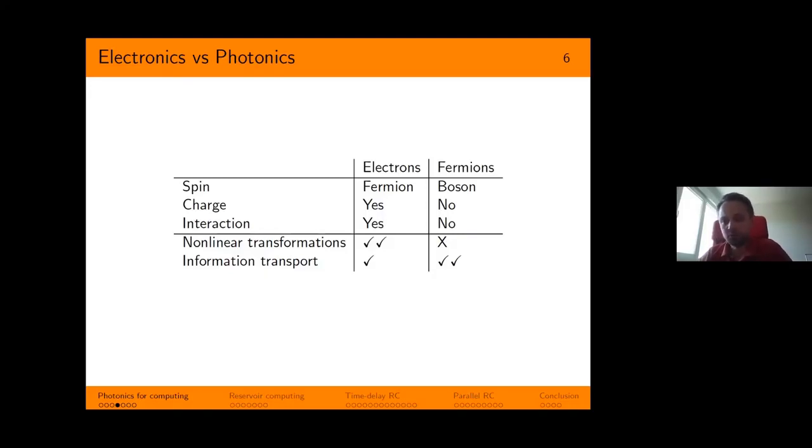The energy just to switch a transistor or to switch a flip-flop in a standard CMOS gate ranges between 40 attojoules and 3 femtojoules. It's a very small quantity of energy. On the other hand, switching an interconnect of 10 millimeters of line consumes 100 times more, 600 femtojoules.